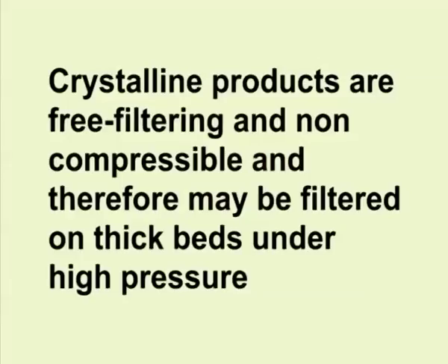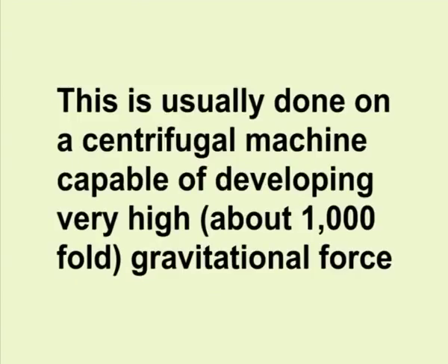Crystalline processing. Crystalline products are free filtering and non-compressible and therefore may be filtered on thick beds under high pressure. This is usually done on a centrifugal machine capable of developing very high, about 1000-fold, gravitational force. The crystals are washed to remove adhering mother liquor. After washing, they are dried by spinning or further drying or solvent removal.